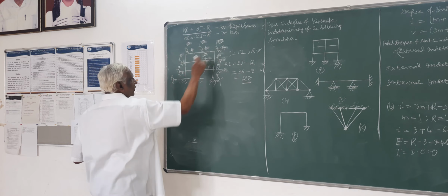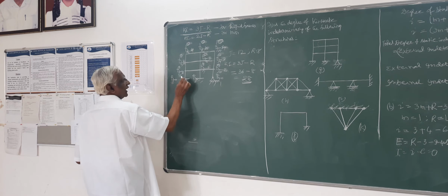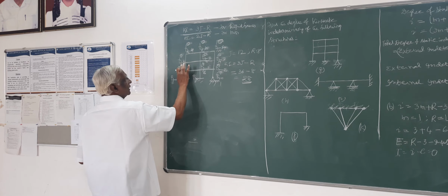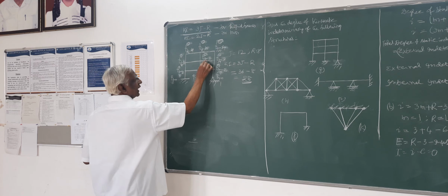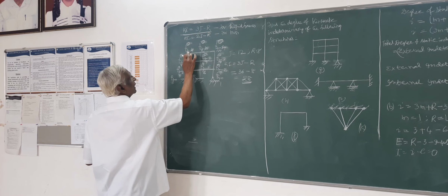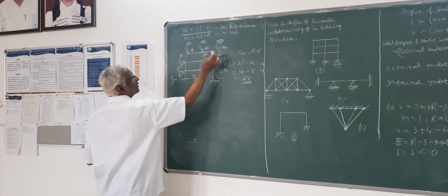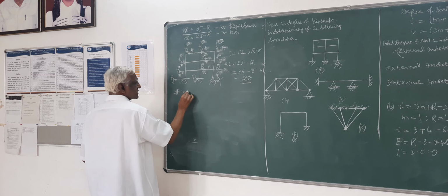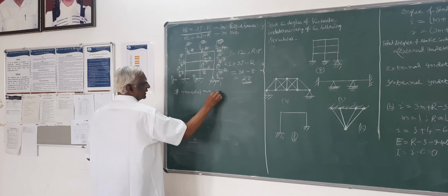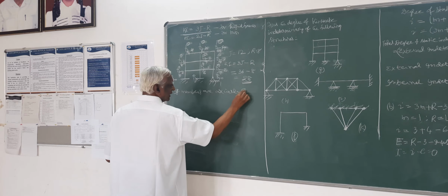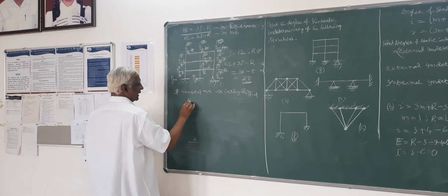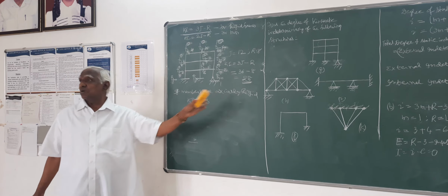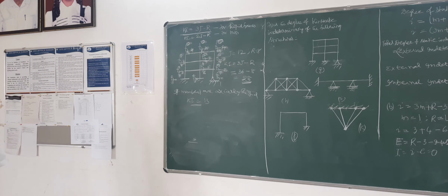Then rotations, 4 is over. So here already I have marked, here this will be 5, this will be 6, this will be 7, this will be 8, this will be 9, this is 10, then 11, then 12, then 13. So these numbers are axially rigid, then kinematic indeterminacy is 13. See, drastically it has reduced from 28 to 13.